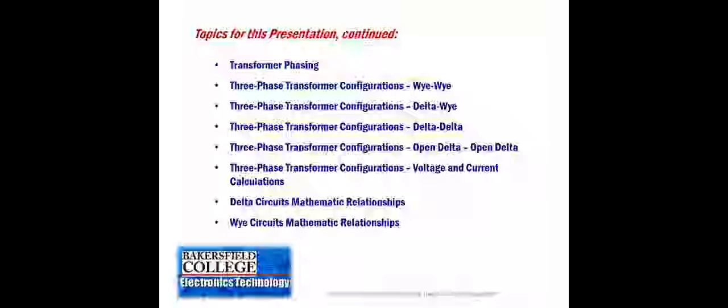So you'll have 65% of the voltage. We'll talk about the importance of making sure that the transformers are correctly phased. So what we're doing is connecting each of the coils of the auto transformer so that we get the correct voltage ratios. Then we'll talk about several combinations of the primary and secondary connections under the low voltage operation. Remember, we're starting the motor at the lower voltage. In this case, we're using the 65% tap.